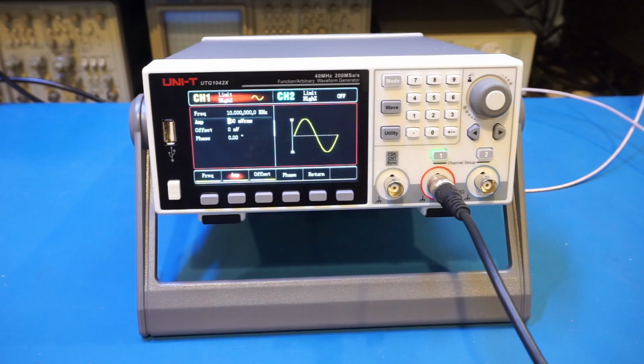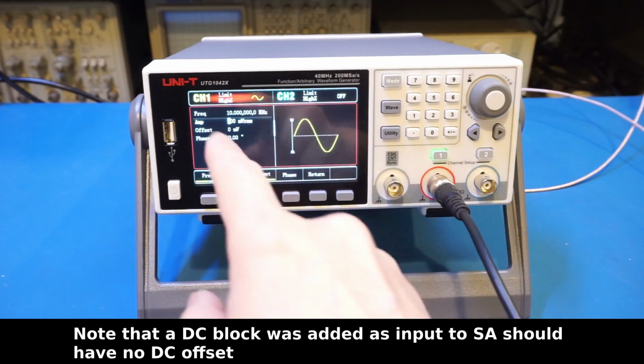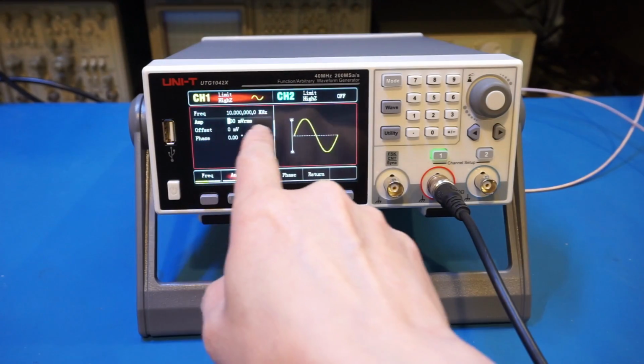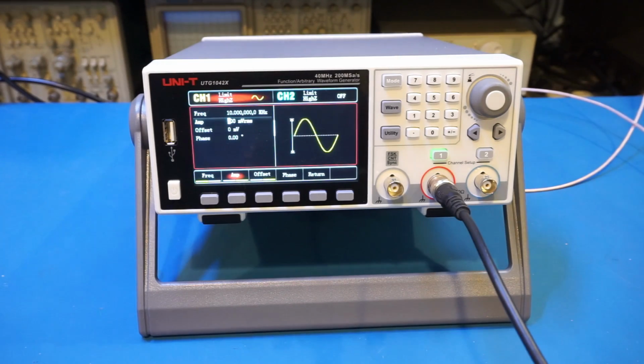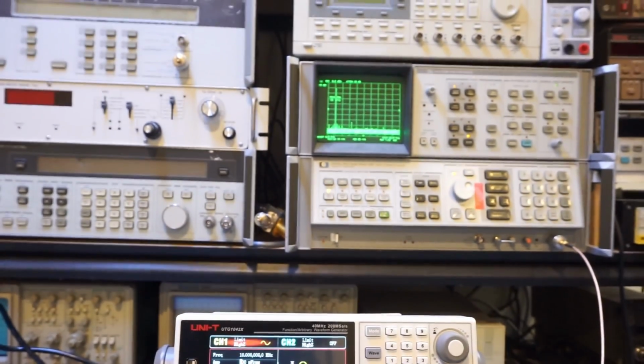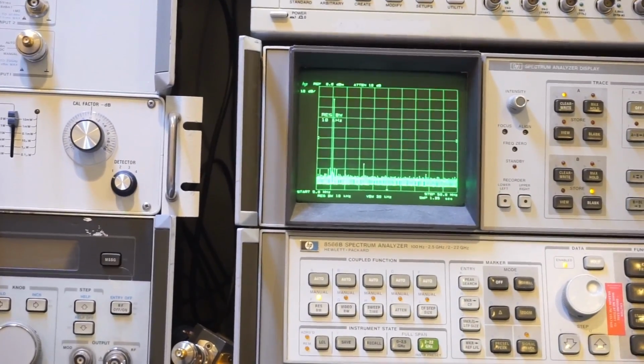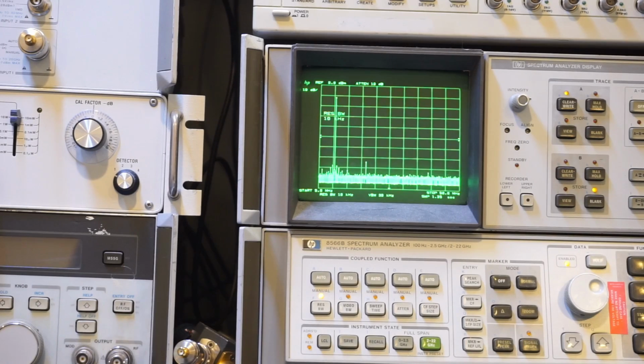What's humming in the background is my HP8566B spectrum analyzer, and currently we're outputting a 10 MHz signal with an amplitude of 100 millivolts RMS, and the actual amplitude doesn't really matter. I just wanted to be consistent with what we're comparing with the 962E. Anyway, let's take a look at the spectrum analyzer here. Currently, it is sweeping between 5 MHz and 50 MHz. You can see we have a very clean tone with very few harmonics around the base signal. We need to remember that as we compare to the signal from the 962E.